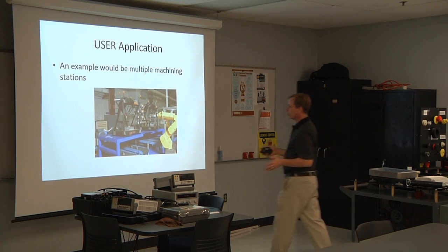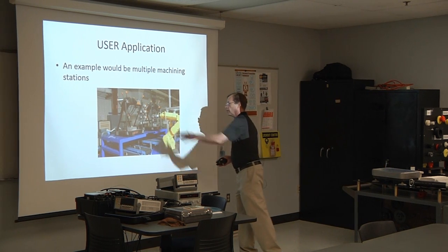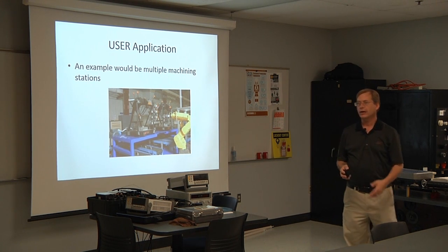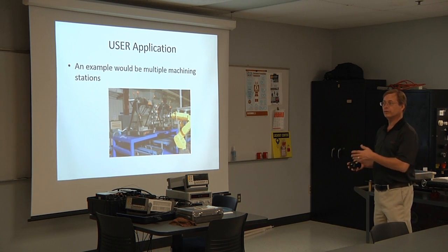So another example might be, I have 2 identical workspaces. I can set up 2 user frames, 1 for each one. I can teach my points and I can copy.